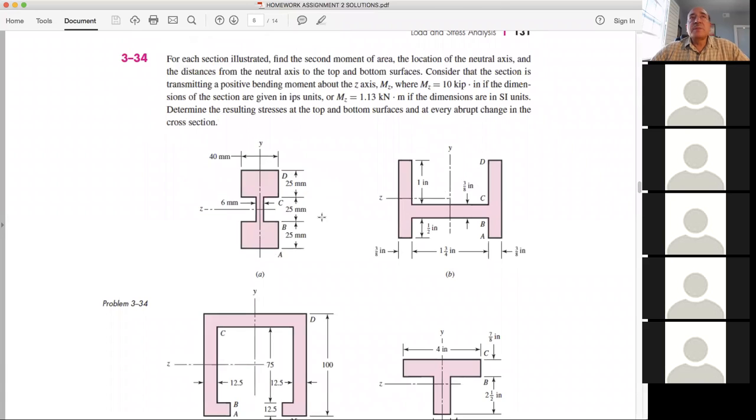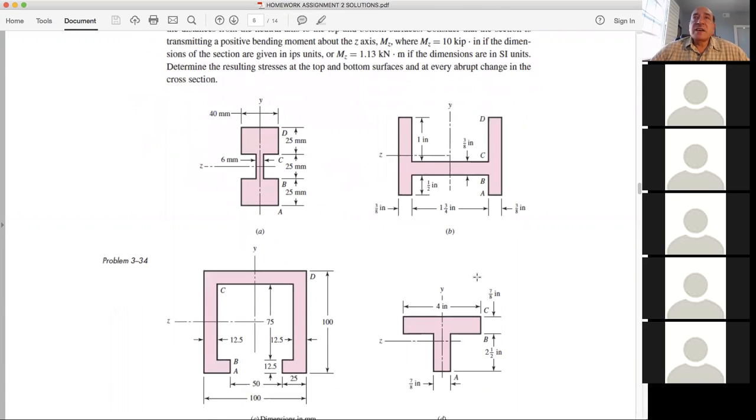another type of problem, these types of problems. You have beams. Now, like the connecting rod will be like an I-beam, could be, or it could be like an H kind of beam. So these are all problems of area. Problems of area, meaning that we want to find the CG, center of gravity, or center of the area, and we want to find the second moment of area.